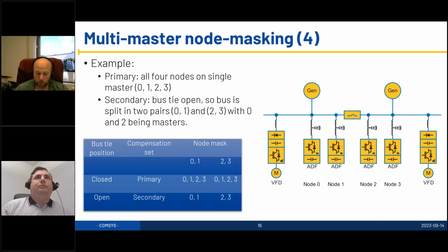And of course, also with reference to the inversion of polarity and the swapping of the individual CTs, of course, if you did mess up the summation CT setup, then you're kind of smoked, and you have to go back in and fix it, because we can't do that in software.